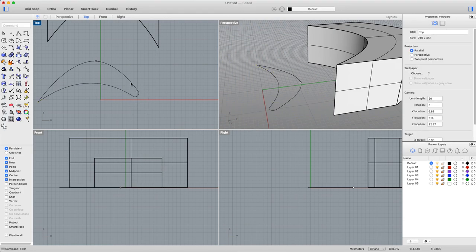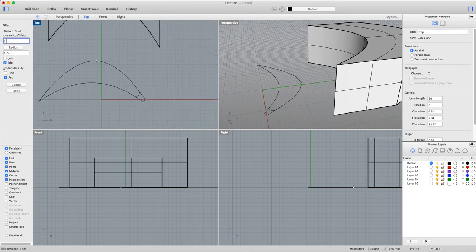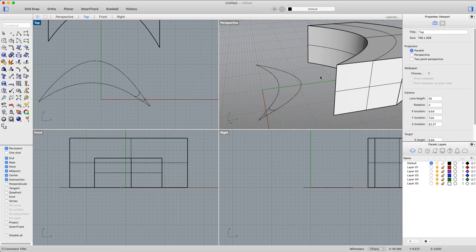It will cut this line and this line to the right length, and it will also extend them if they're too short. So if I do it again and I create my fillet a bit smaller, it will extend this line and this line so that they join together. Okay, and if I put 0, it will make a hard corner like that. So that works the same way for fillet a solid, which is called fillet edge.